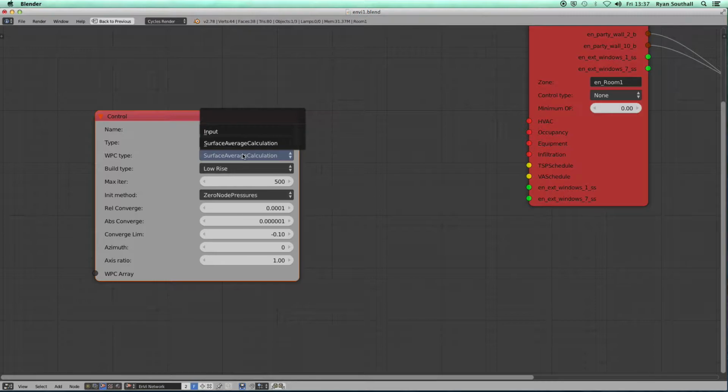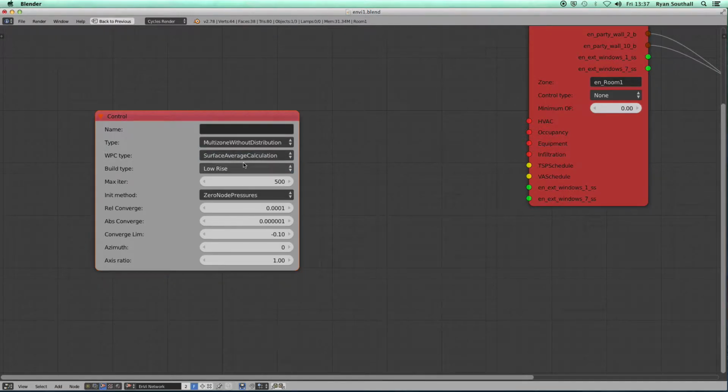the flow that comes in or leaves the building through these different airflow surfaces is defined by the pressure conditions outside the building to a large extent. And those pressure conditions outside the building, they can either be calculated automatically by EnergyPlus, or we can input through a wind pressure coefficient array. But I'm just going to use the inbuilt EnergyPlus calculation for the moment.